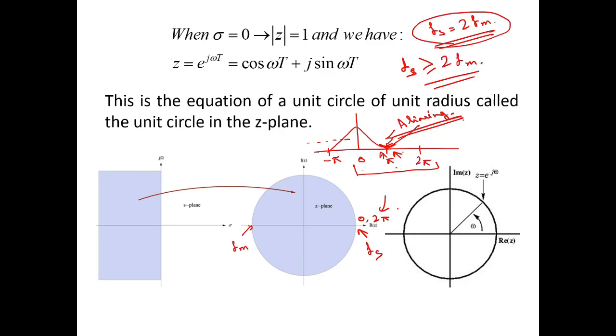And once aliasing happens, your signal is totally corrupted, you cannot use it. So even though theoretically it is told that your fs should equal 2 of fm, if you increase the fs, it would be better for you, as it will help in eliminating any chances of signal corruption.